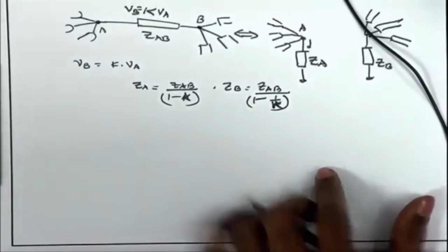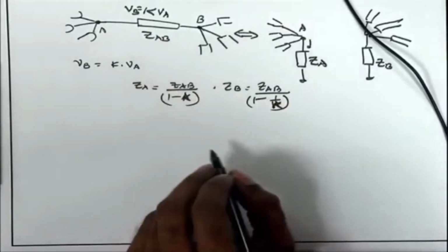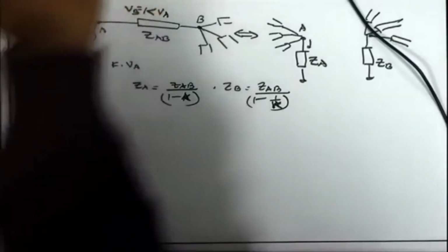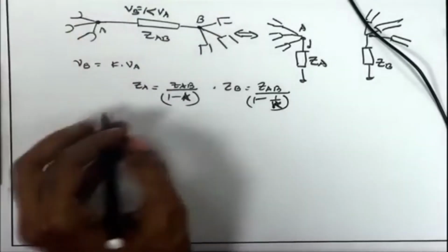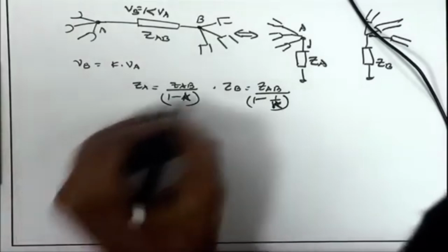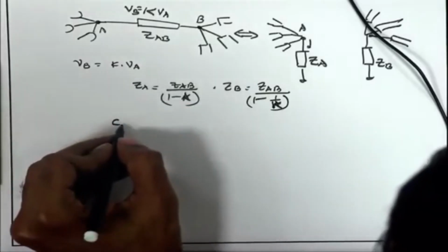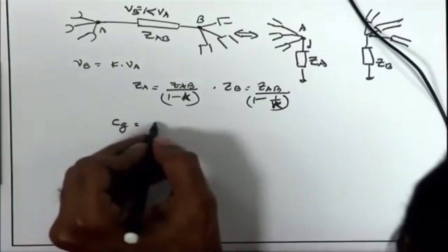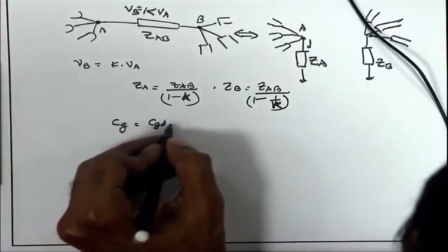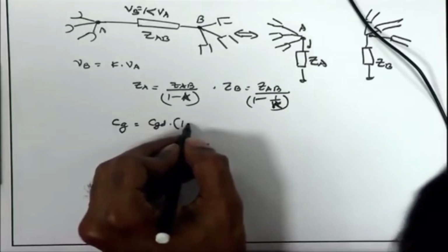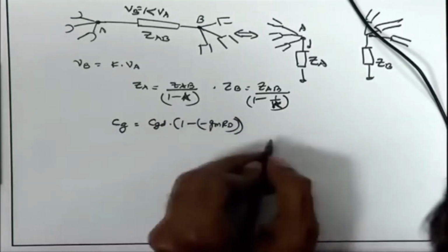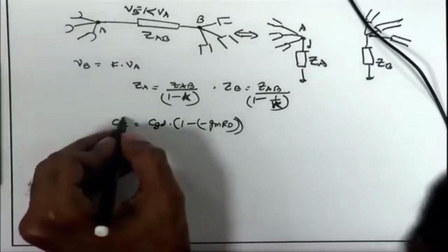and therefore, the equivalent capacitance, if I look at the impedance, that is 1 upon SC. So, by this analogy, the equivalent capacitance becomes multiplied by C. If I have to find out CG, that gets multiplied by CGD times 1 minus A, that is, 1 plus gm RD, and likewise this is the CG dash which I am putting here.